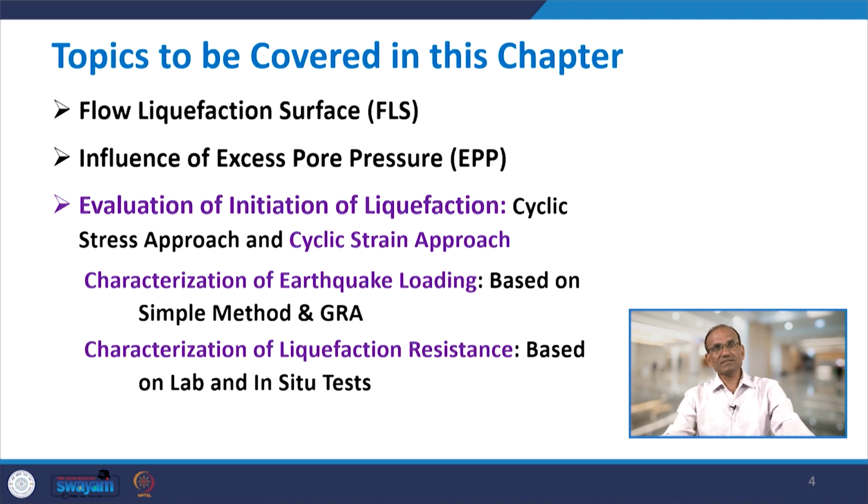Under this third chapter, we already discussed flow liquefaction surface, FLS, and the influence of excess pore pressure has been already covered. Then we talked about how to evaluate initiation of liquefaction, and there were two approaches: one is the cyclic stress approach, another is the cyclic strain approach.